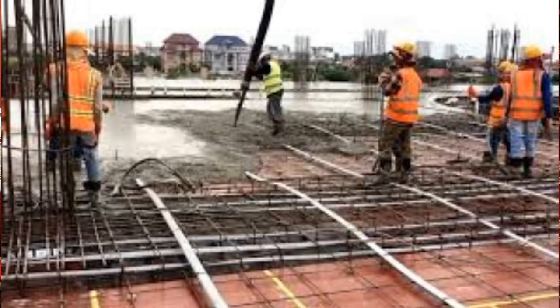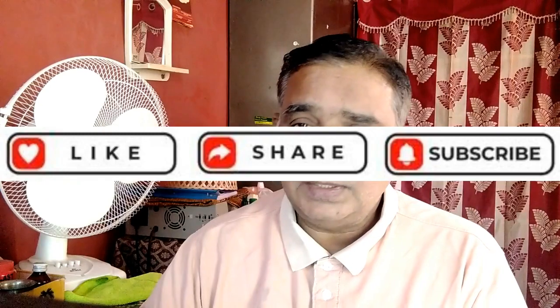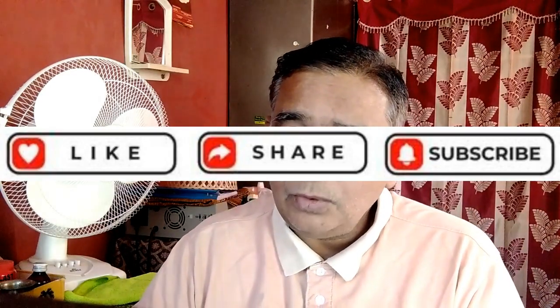Flat slab systems for buildings. Flat slabs are similar to flat plate, apart from thickening of flat slabs around columns, which is provided to improve shear capacity of this floor system. Flat slabs are economically viable for spans ranging from 6 to 9 m, and live loads ranging from 4 to 7 kN/m².